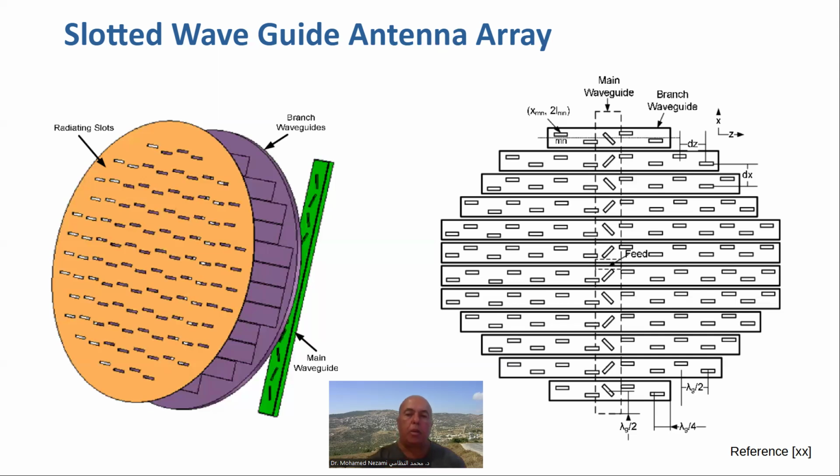And it was then that we introduced the concept of a slotted waveguide array, where we have a bunch of rectangular waveguides, and then we put slots at some predetermined spaces with certain dimensions in them, and then we feed them all in a predetermined, engineered way, and then we can produce the complete aperture that is used for systems such as radar and satellite communications.